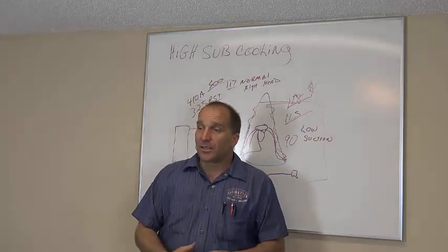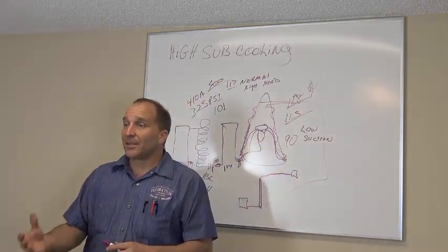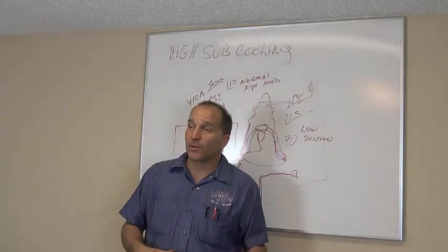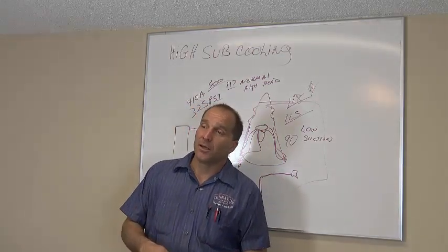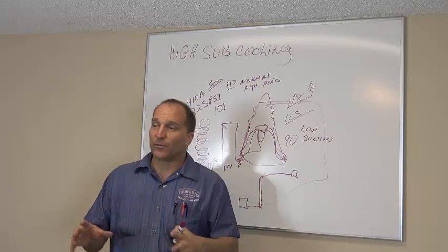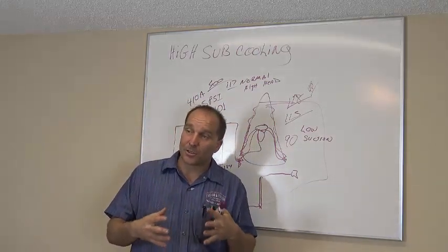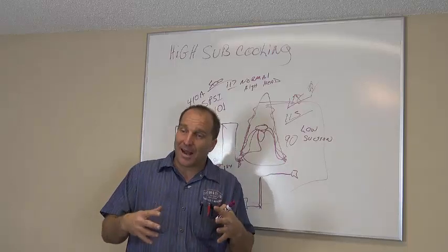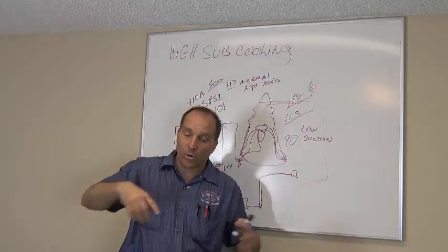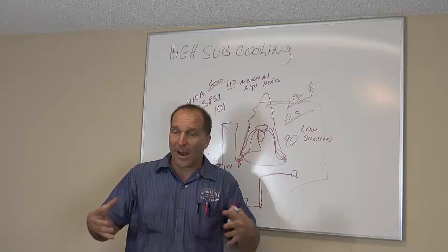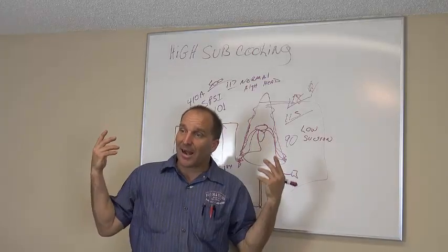Ryan, I went and checked out your system just a few minutes ago, and one of the things I was checking out, man, your condenser is filthy dirty. Let me explain to you what the condenser does. The condenser takes the heat from inside the house, brings it outside, and the compressor pumps that gas into a hot gas. As that hot gas runs through those condenser coils, the airflow going over the coil disperses that heat outside.